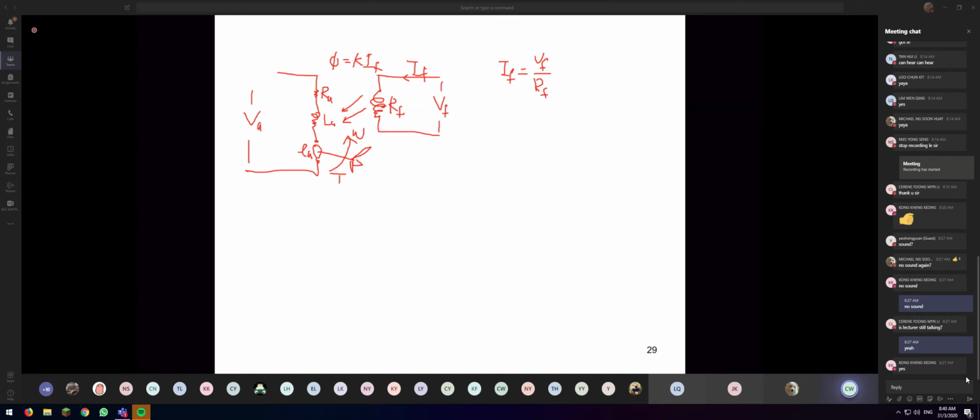Okay, KIF. That means this will give me the so-called adjustable flux into my armature. So let's say if I want to increase the torque of the motor, right? Actually, I can control the field voltage, or I can control the armature voltage to control my field current and also the armature current, so that I can control the torque. So this is actually the advantage of the separately excited DC motor, because they have adjustable torque control and also speed control by adjusting your field winding.